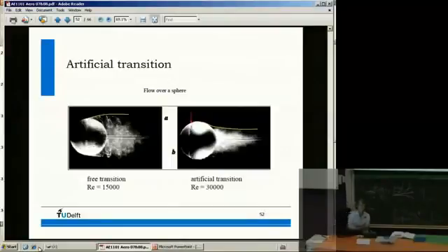This is a very nice picture that can illustrate it. Turbulent flow has all these small eddies, so it has energy in all directions. So it has more energy to fight the adverse pressure gradient. So although turbulent flow has higher friction, it has later separation. So here you see a ball with no turbulent flow, so laminar, very smooth edge, and then the flow separates here.